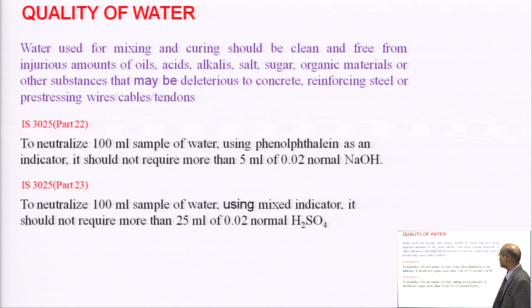And I had earlier spoken that the Mandovi Bridge in Goa collapsed during working condition in 1986, because they used not water, but an admixture which was carrying chlorides. In working conditions, that admixture they used for grouting the tendon, and that tendon caused corrosion due to the effect of chloride. So, if water also has a higher percentage of chloride, certainly it is going to create a problem.